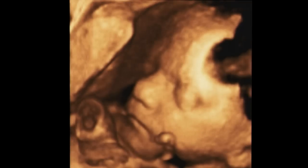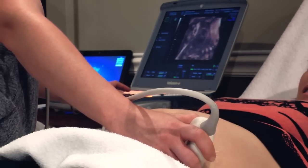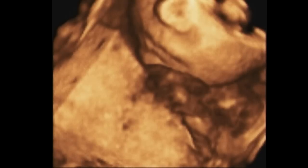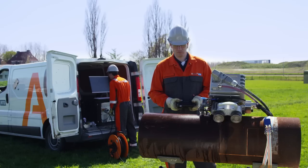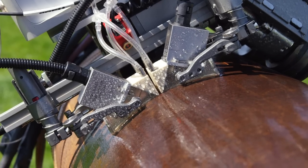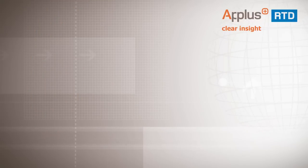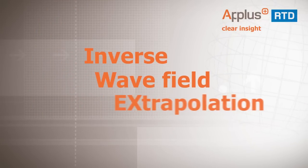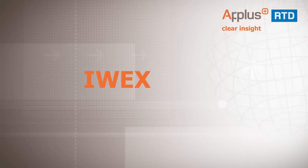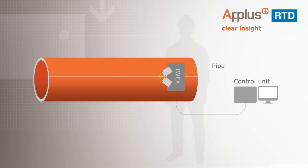Inspired by techniques regularly used in other fields, which transform ultrasonic signals into a clear 3D digital picture of what's beneath the surface, Applus RTD has developed, in the range of NDT 3D, the RTD IWEX. IWEX stands for Inverse Wave Field Extrapolation. Its purpose is to scan seam welds for defects using ultrasonic array technology, based on full matrix capture.